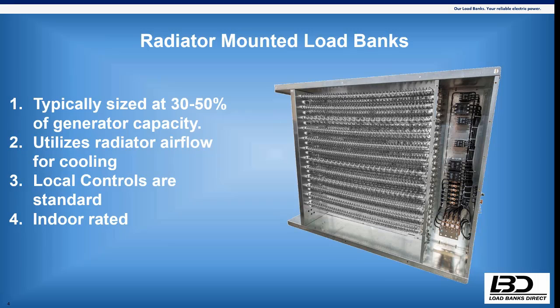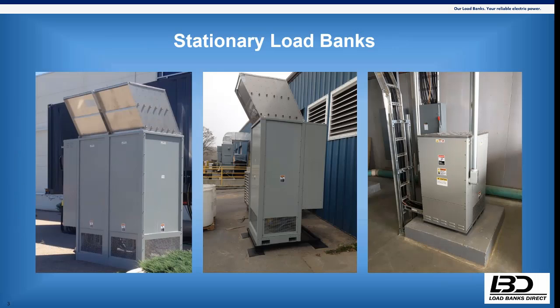We all know that generators are tremendously oversized. People use a 1,000 kW generator in an installation, and they may not even have 200 kW of connected load. So the ideal solution is to have a stationary outdoor load bank like the one on his previous slide, which has its own cooling fan. It's bigger, and it's obviously more expensive.